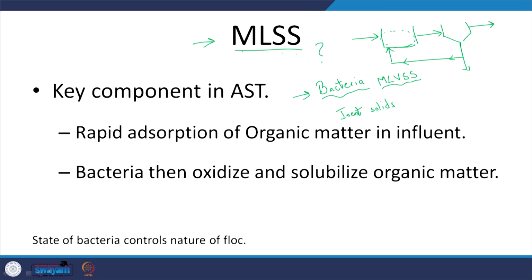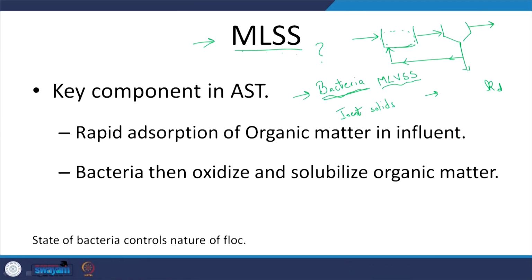And in this MLSS, what else? Is it only bacteria? No, it looks like you will have some protozoa, 5%, and they also feed on the bacteria. So that's why you have the decay coefficient Kd, right? So that's one aspect, and protozoa seem to be playing an important role in leading to good sludge that can settle. So that's one aspect.